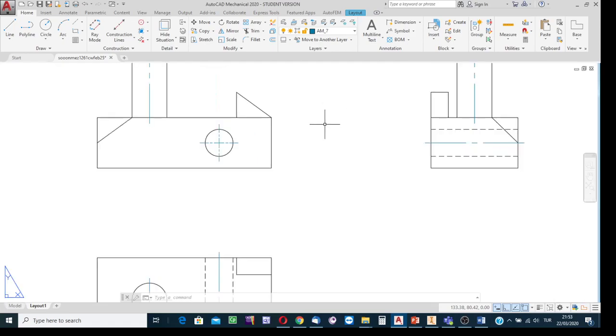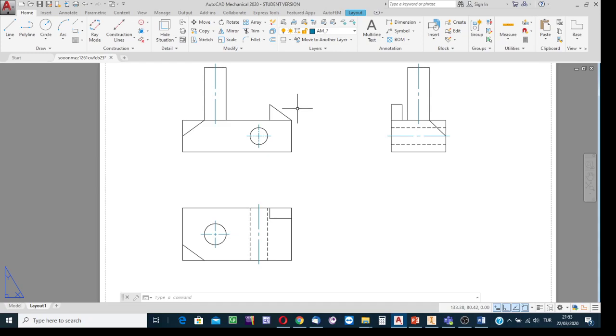Well, to be able to draw the attention of the reader that the line is not a continuous line but an axis of symmetry, have more dashes along its line of action. To be able to change the length scale for a certain line, use this technique. Select the line with a click. These are the lines for which the length scale is going to be changed, and then right click the mouse.